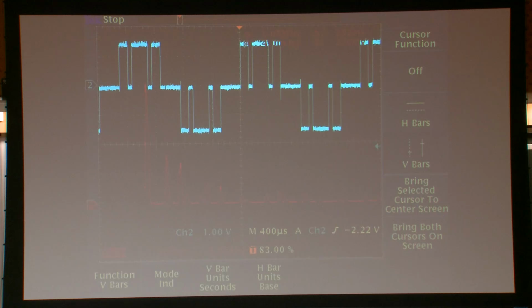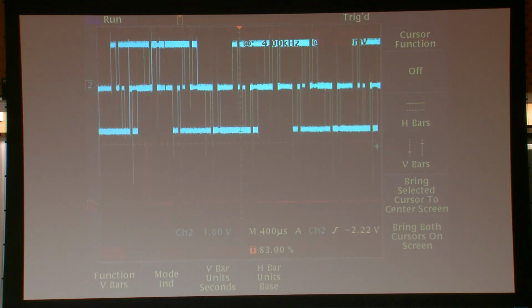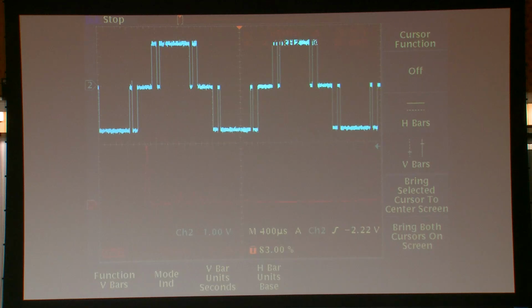Now we can take this a step further. Let me run it and stop it. Okay, now if we move all the way back, the second spike occurs at 5.3 kilohertz, which is the ninth harmonic. So we eliminated all the lower third, fifth, and seventh harmonics.